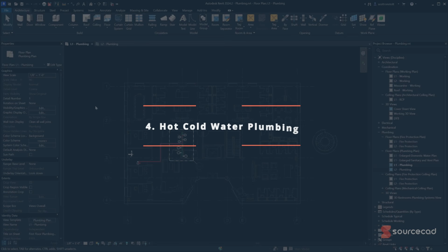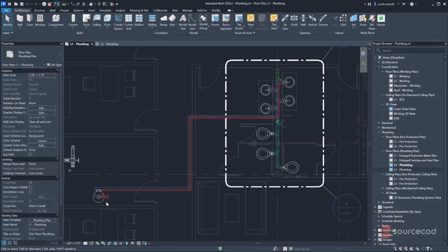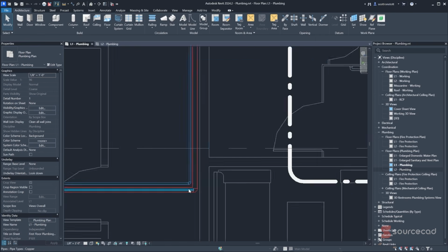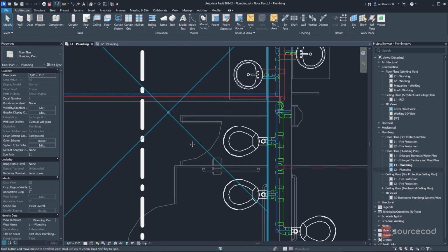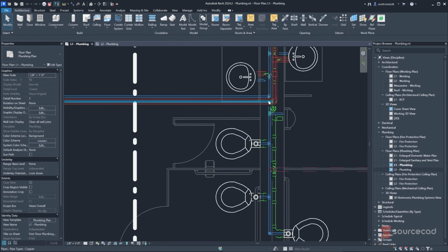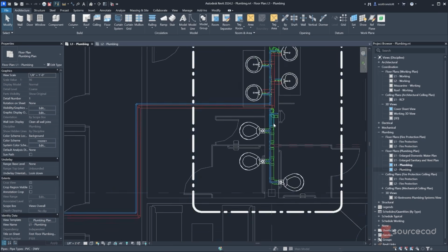I've opened the plumbing model, and if you look at level 1, you can see what was done there. We see a hot water heater over here in the systems room with hot and cold domestic water supplies. The hot water is shown with insulation, and that's why it appears thicker. And that is routed through the ceiling down into this cavity in this wall between the restrooms. And you see below all of that, you'll see the sanitary piping in green.